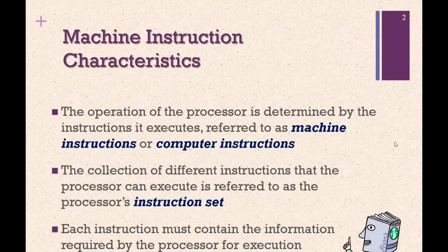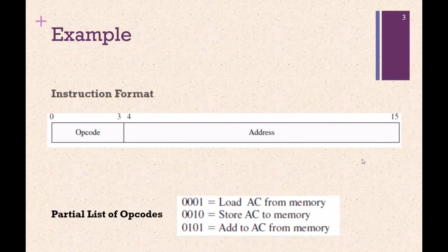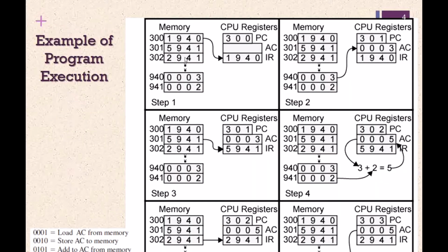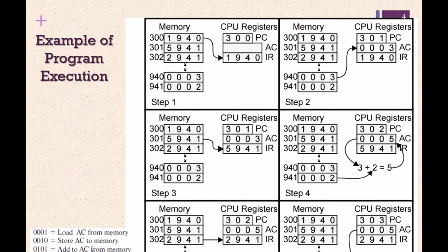For this purpose, we see in the next example, in which the first field is the opcode and the second is the address side. In this example, we load the memory location 0001 into AC, then store AC into the memory, and then add this into AC.